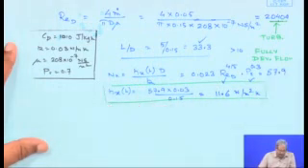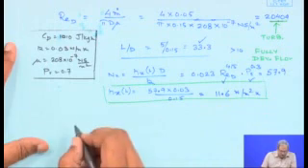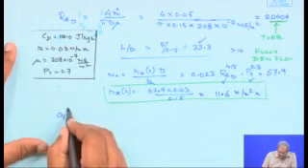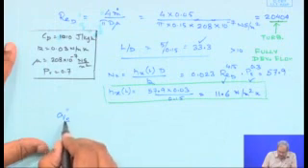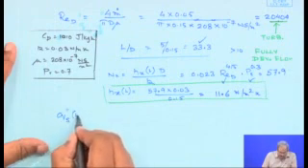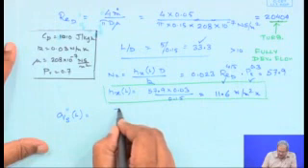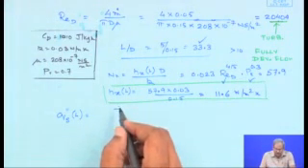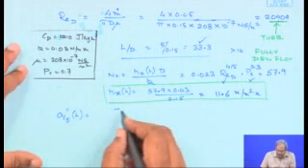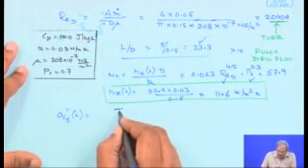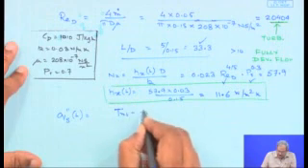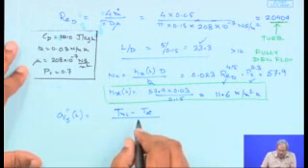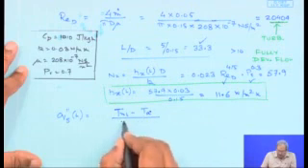So that's the value of the heat transfer coefficient for this specific situation. My heat flux, which is q double prime s, the surface heat flux at location L, as I have shown before, is simply going to be T_m,L minus T infinity, divided by 1 by h_x,L at location L plus 1 by h_0. Recall the figure which I have drawn in the previous page.